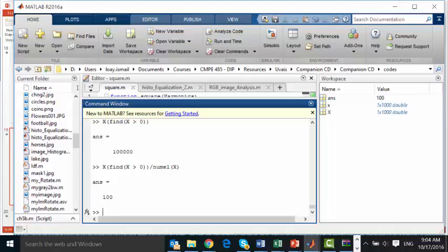Yes, about the average. If I want to get the actual values of the frequency components, when I say x of 1, which is the first element in the result of the Fourier transform, this will give me the amplitude of the zero frequency. Zero frequency means I am talking about the average. What is the value that does not change?